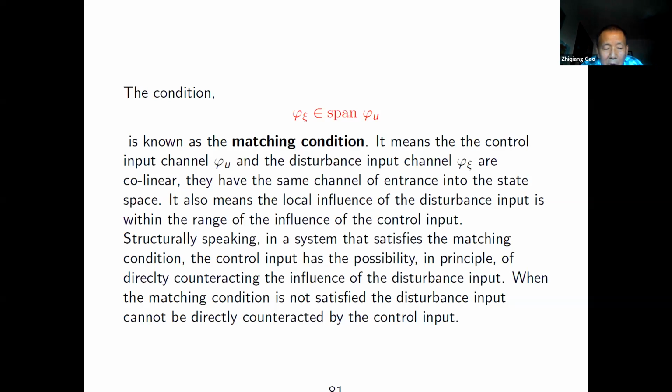Okay. Yeah, can I understand this in this manner? Since we're talking about motors, by doing singular perturbation you are separating fast dynamics from slow ones. And you may discover in AC motors, for example, that your voltage line fluctuation is on the electrical side, and you are charging the inductor with voltage. So that voltage fluctuation can be canceled by your supply voltage. So that's a cancellation on the fast dynamics.